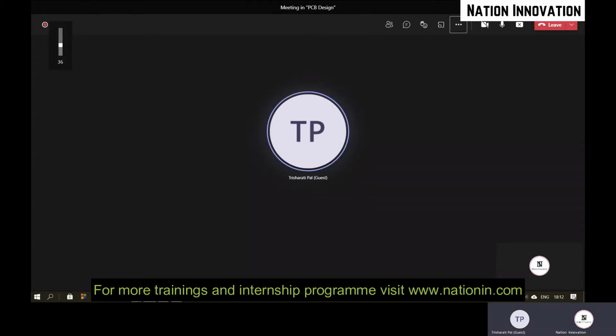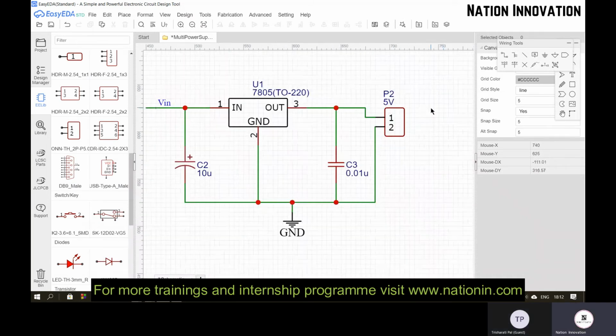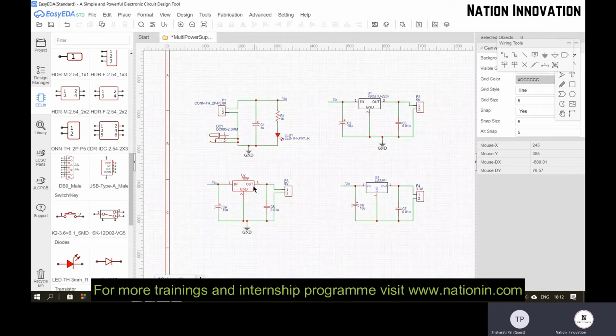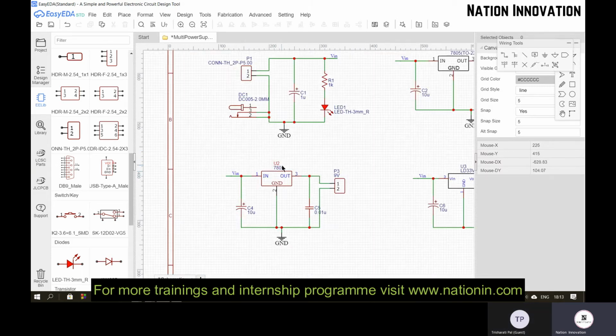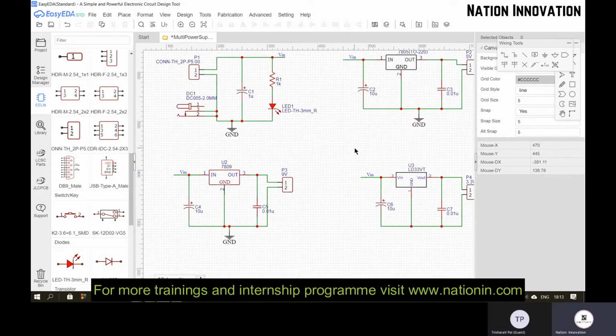Yes, ma'am. Okay. Ma'am, the 7809 IC is for which power supply? To get the 5 volt, 7805 IC is used. And 7809? It is for the 9 volt voltage regulator. Okay. So the last digits indicate the output voltage of this regulator. Okay, and this is 3.3 volt.